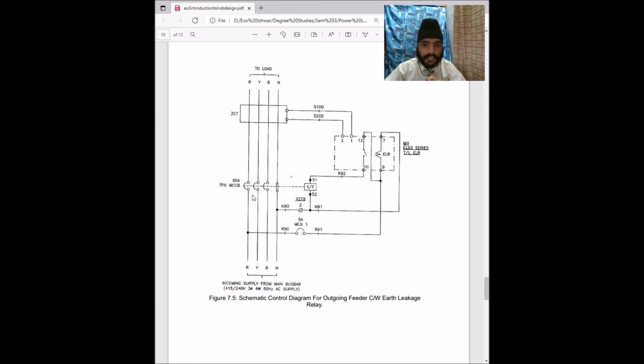When it is on, it will make contact and our load will get the supply. This whole circuit here is the protection circuit, which is the earth leakage relay. The ZCT component here is a zero phase current transformer. ZCT series are compact molded type zero phase current transformers, ideal for improving the sensitivity, compactness and weight of electric shock prevention.